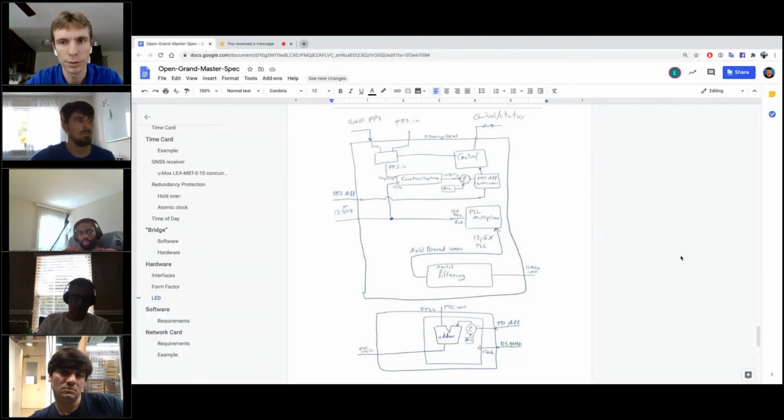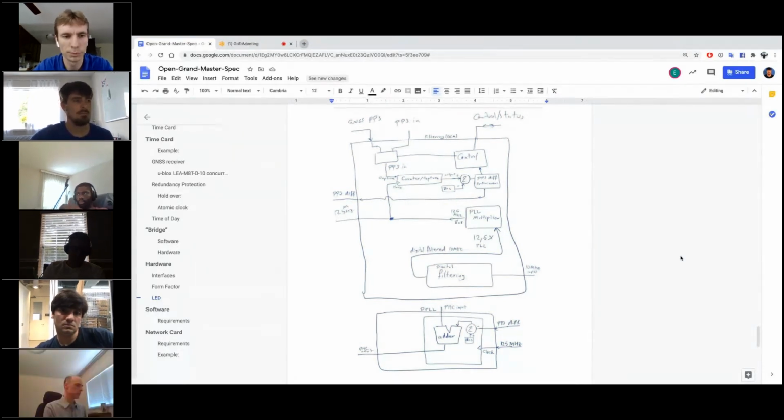Yeah, it's just very interesting because we had a lot of discussion about the FPGA. I've encountered one of the requests because we do have TCXOs with digital control interface, and one of the 1588 vendors, companies that deal with 1588, wanted to use our parts to digitally pull the oscillator with fine resolution and improve their adjustment resolution from, I think they had 4 nanoseconds, and they wanted to drop the discrete step and go with much finer resolution. Absolutely. So that's why it triggers the interest.